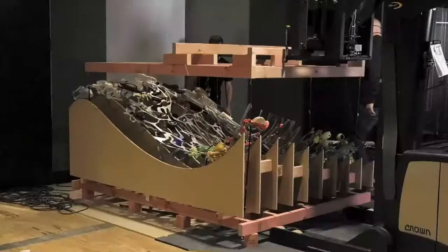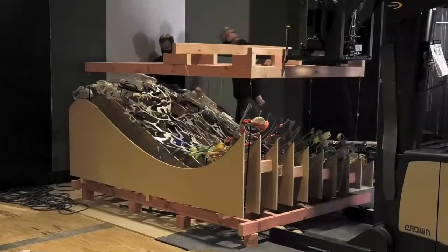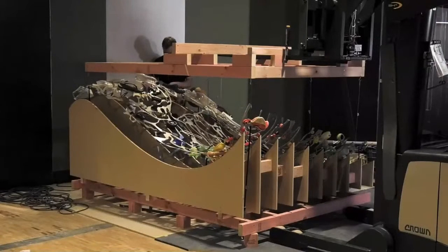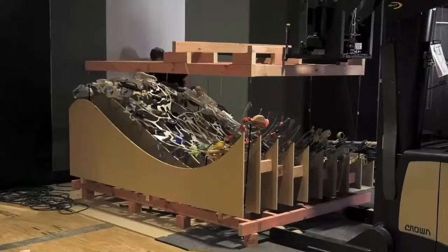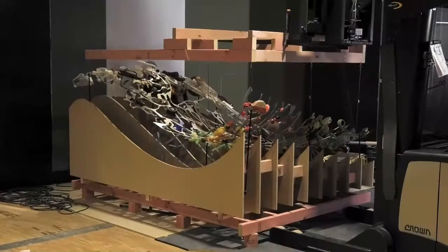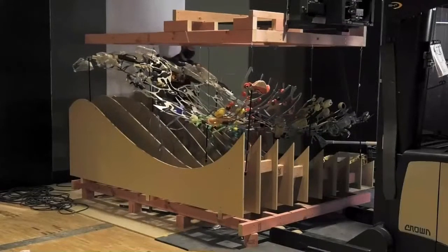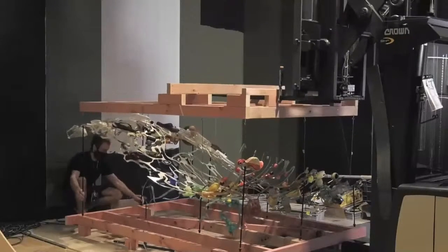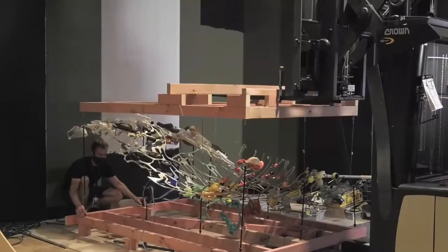So the formers allowed us to move it around, but to get it into the case, we made a stretcher to pick it up from the tops of the uprights and spread the load nice and evenly so it wouldn't deform when we pick it up. And that would allow us to slide it in using a forklift, slide it into the short end of the case, which is the door, and just drop it, and we can guide the uprights into their holes in the